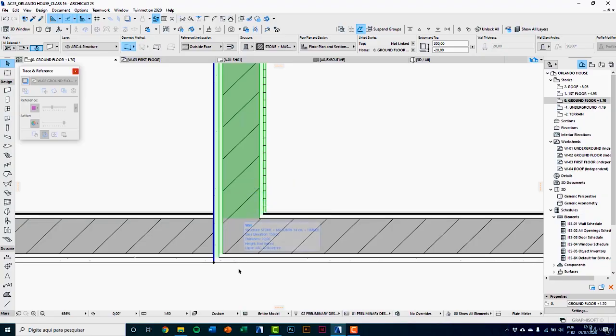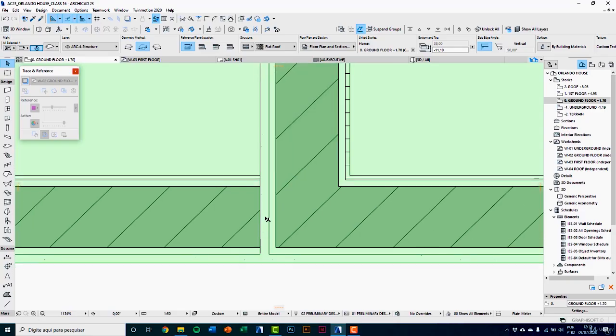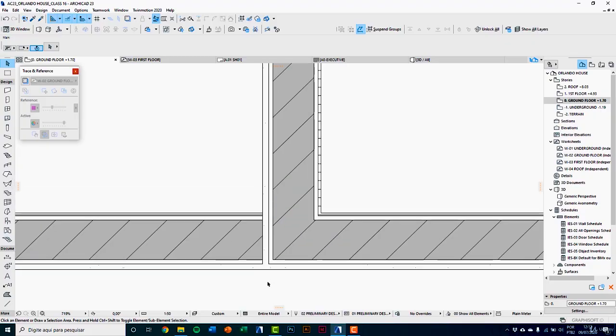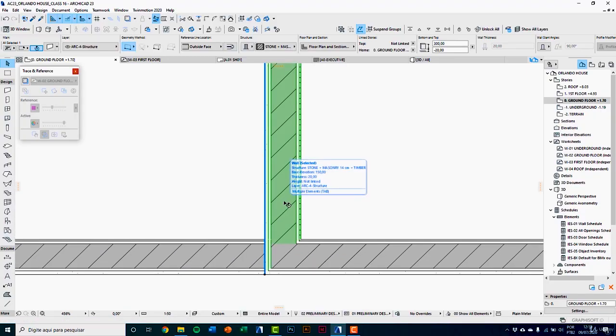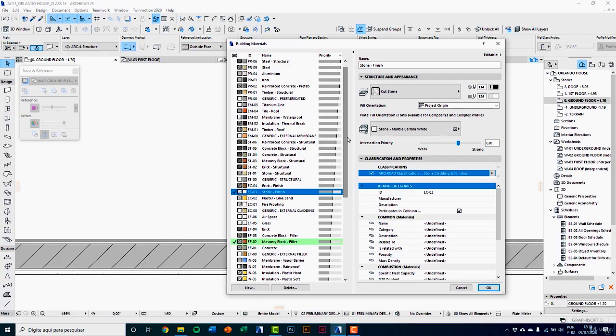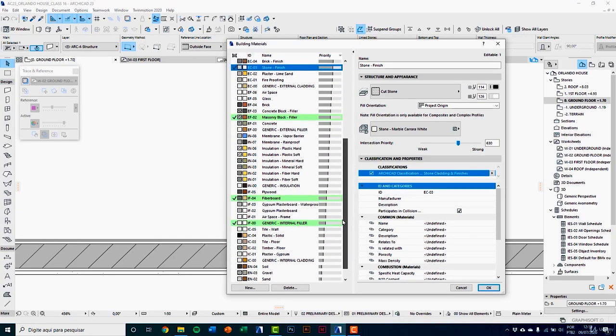And even intersecting the reference lines of these walls, you see that finished materials doesn't allow that masonry blocks be united. It is happening because these finished materials are with higher priority than masonry block. Select the wall and go into building materials again. The materials belonging to this composite structure are highlighted. Clicking on priority, we can see the materials listed by priority order.